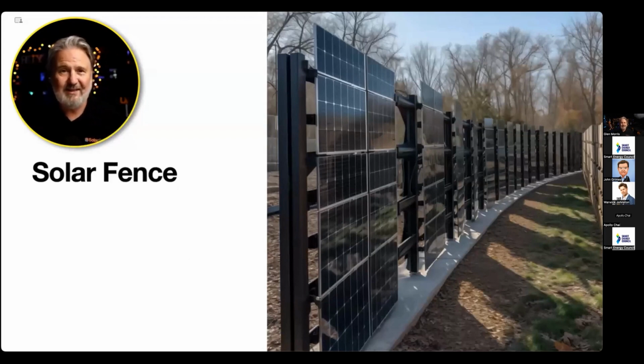Solar fences can be installed, but there are a few caveats. Now, in Australia, we have a standard for PV arrays called AS/NZS 5033. And since the update, the 2021 edition came out, it says that you have to have restricted access to all of the DC parts of a PV array up to the disconnection point. And that includes the cables behind the panels. Now, what is restricted access?